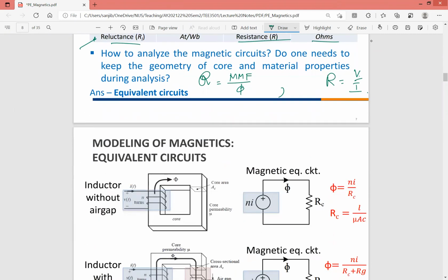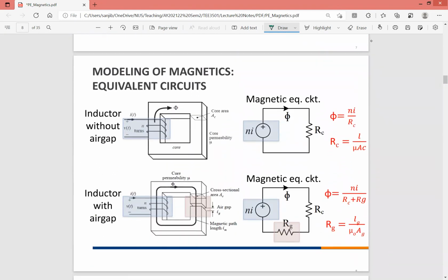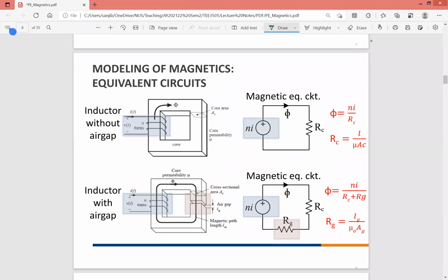Okay. So here it's given pictorially. The equivalent here, you can clearly see that everybody must be clear about it. That electrical circuit we all know is the magnetic circuit. So you can see the source, see the effect. So the magnetic conductor, which is basically called the core, is represented in the electrical circuit by the resistance. So this relationship. Now, the core reluctance would be given by the length over mu times area.